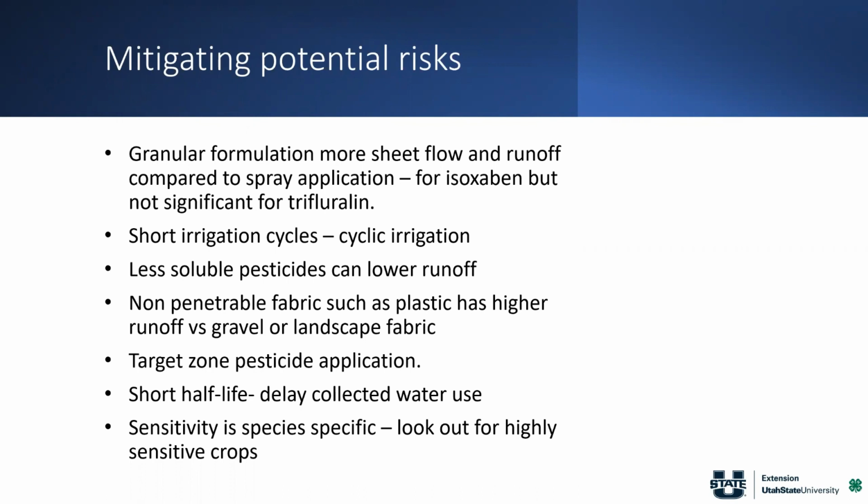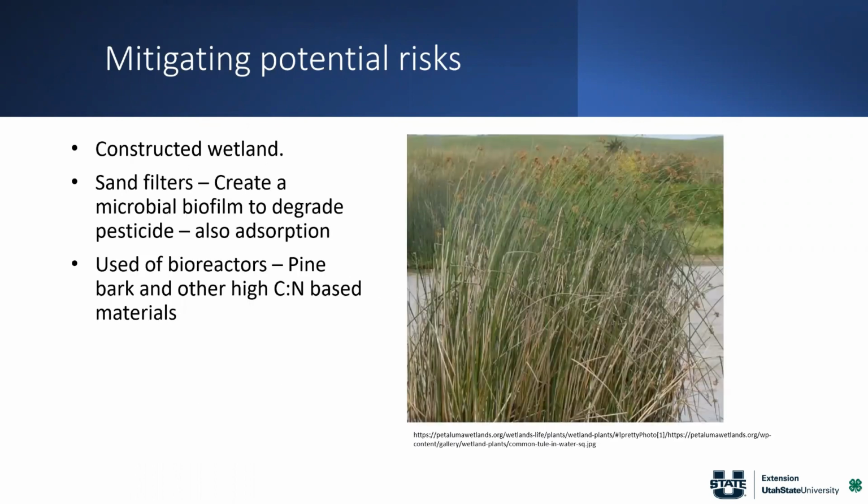And also sensitivity is species specific. So whenever you are using the recycled water, always trial with a few plants first. Maybe you can have a zone, put 20 different types of plants that you grow or that your landscape has, spray in there, see which plant is having damage, and then you can select and apply on the plants that are not having damage. So these are the ways how you can mitigate risk.